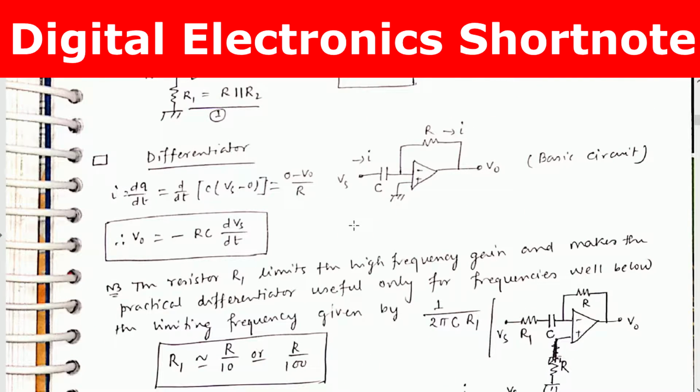This is the circuit of a differentiator. Here the capacitor is connected at the inverting terminal, and I equals dq by dt equals d by dt of C into Vs minus 0, equals 0 minus V0 by R. Therefore V0 equals minus RC dVs upon dt.